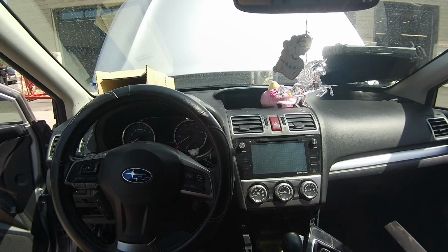There's my 15 amp fuse. And I'm going to come down here. I want to see. There we are. MB28 supplies power to the key warning switch, the turn signal and hazard unit, and the body integrated unit. So the BIU is tapping into that 12 volts to get that solenoid to power up. I also said my key warning switch too.